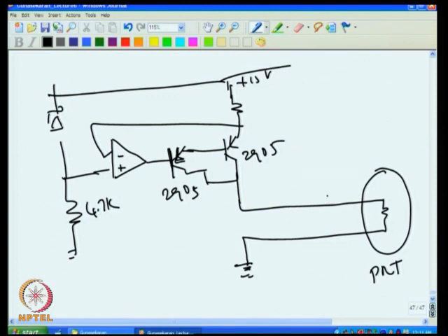But then these connecting leads, which are actually this one and this one, if they are longer, then they also add a resistance. So if I try to measure the voltage between this point and this point, then I am measuring the platinum resistance thermometer's resistance plus the copper wire resistance. The problem with this copper wire is the copper wire also changes with temperature. Maybe this is in room temperature.